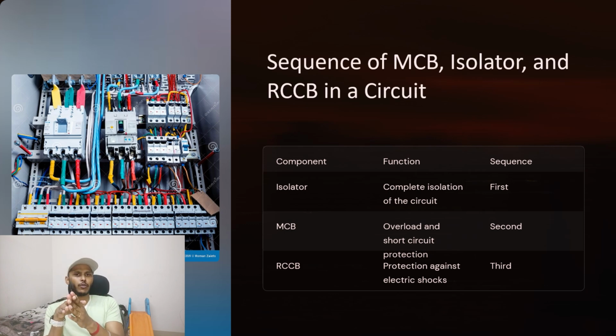If you want to isolate the complete power, you can turn it off. Whichever system you have, the RCCB, MCB, single pole MCBs, the complete system, if you differentiate it as a field thing or a customer or client thing and our thing, the client side will be separate and our side will be separate. There is no interlinking, so you can make that kind of segregation if you put the isolator first.